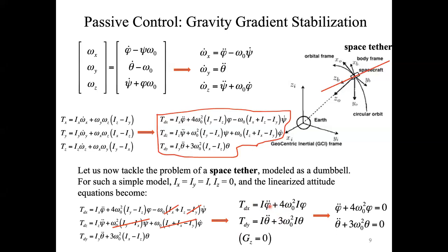So basically just two equations, because you don't have any control on the y-axis. You are assuming here that the z direction of the body is going to be aligned to the y-axis. So you can see that for this configuration of the moment of inertia, since you don't have any inertia of the body in this direction, the gravity gradient doesn't give you any contribution.